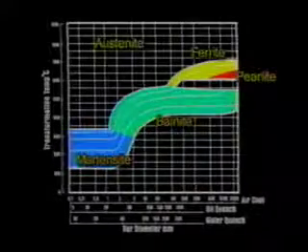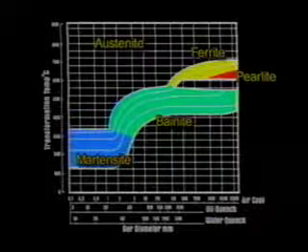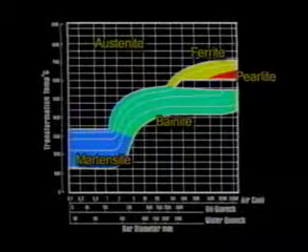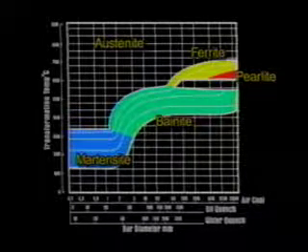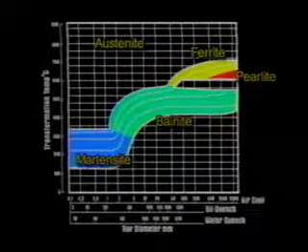Using a continuous cooling transformation curve, or CCT curve, for the steel of interest, the critical cooling rate that must be exceeded in order to minimize pearlite formation is the cooling rate just to the left of the nose of the pearlite transformation portion of the CCT curve.